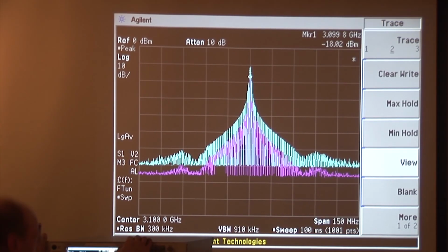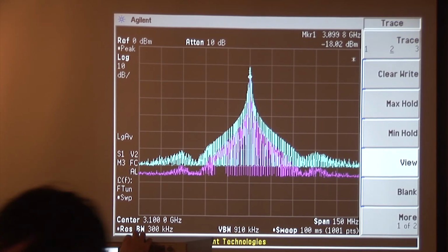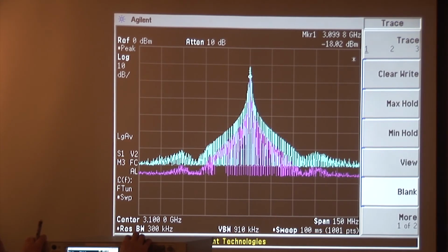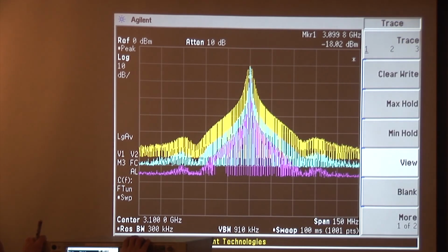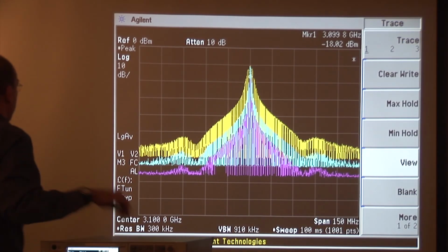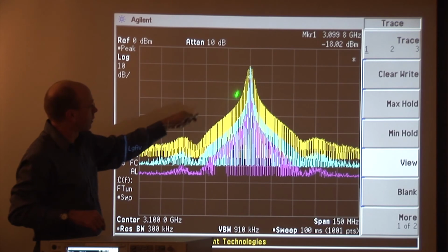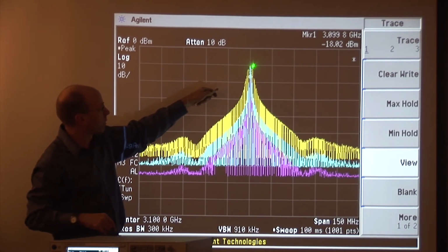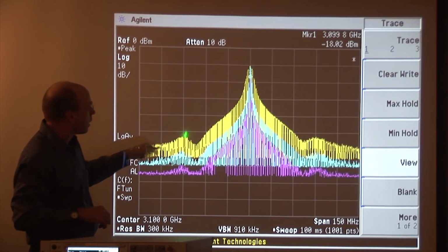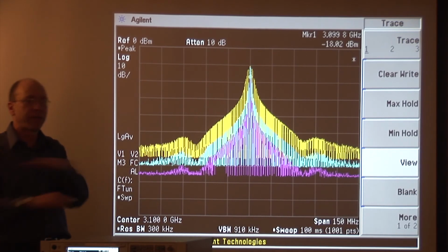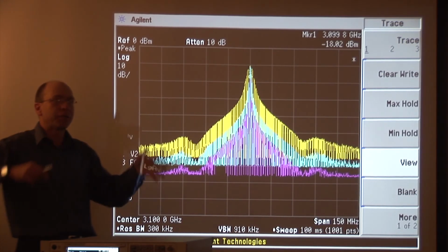Because if we go greater than 1 over the pulse width, as we will recall, I'll just bring it back. We come back here to the yellow, and we go view. Here's our measurement in 3 megahertz. Because remember, if we go to this wider band of 3 megahertz, we don't get any more power here, but these levels just keep coming up. So my joke is that I can make any radar fail the RSIC by measuring it in too wide a bandwidth.